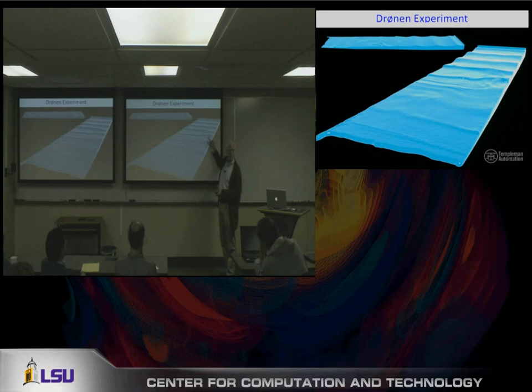So there's wave current interaction. That outgoing flow is slowing the incoming waves. So now I got wave current interaction. So I've got wave breaking, wave refraction and diffraction because of the depth changes. So wave breaking, wave refraction, wave diffraction, wave current interaction, harmonic generation, set up, run up.